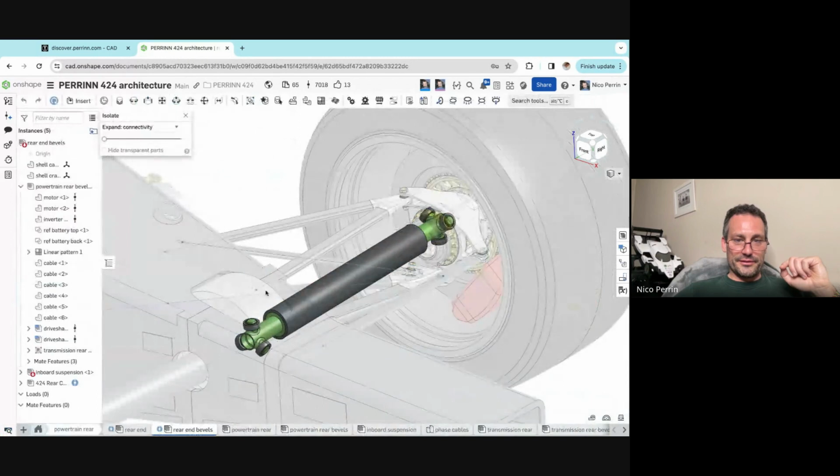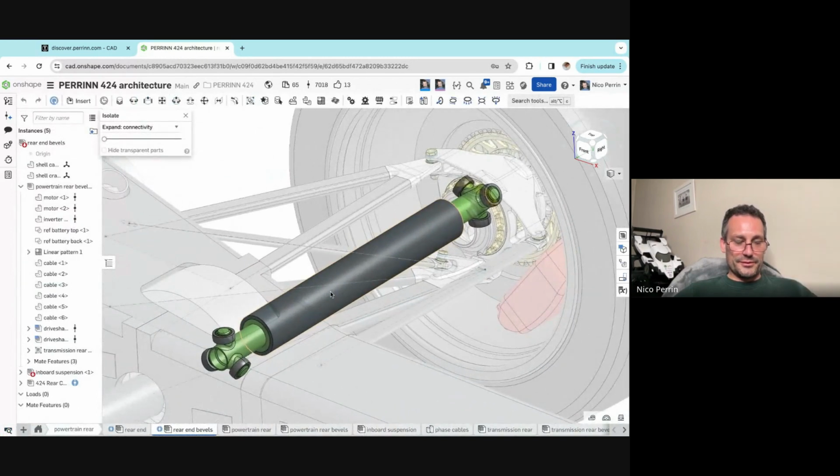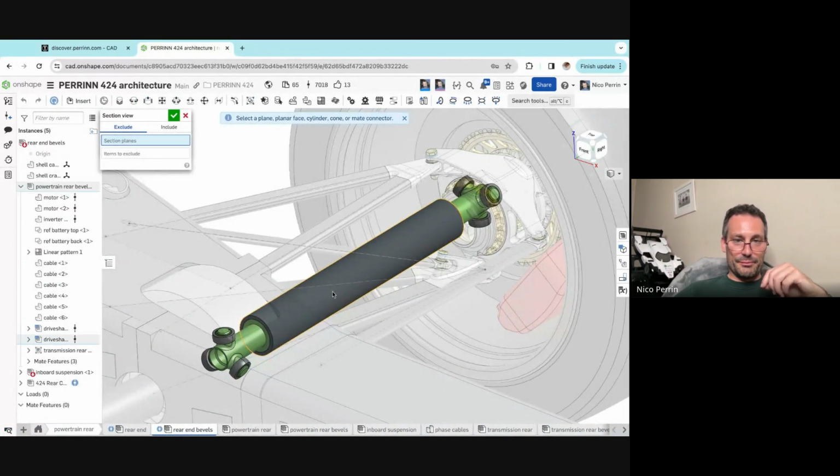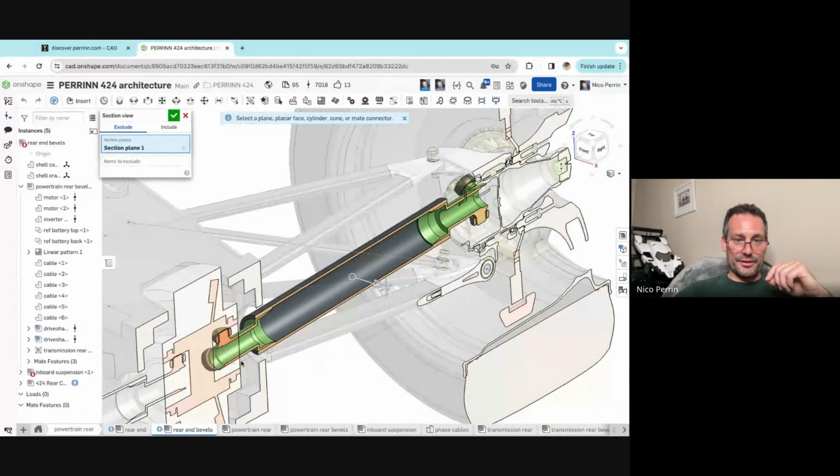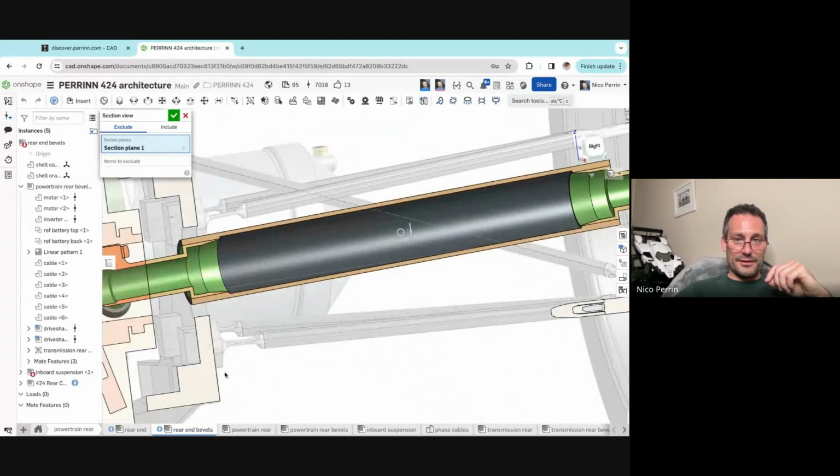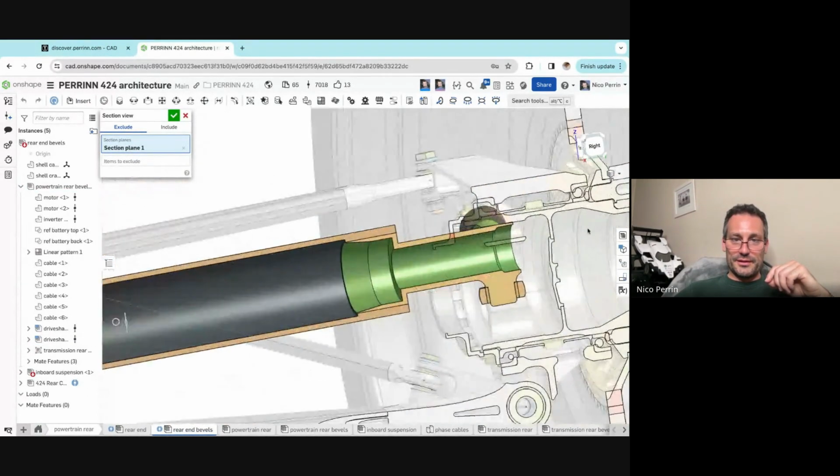This is quite a nice model here. You have a more accurate model of the thicknesses. In fact, it shows you the thickness of the tube, which I've calculated from knowing the torque going through each wheel. And I wanted again to have a mass for the drive shafts. They can weigh 2 or 3 or 4 kilos, so it's quite important to know them.